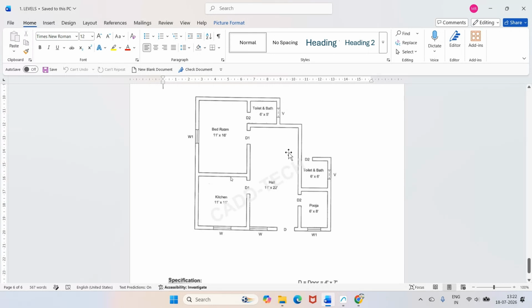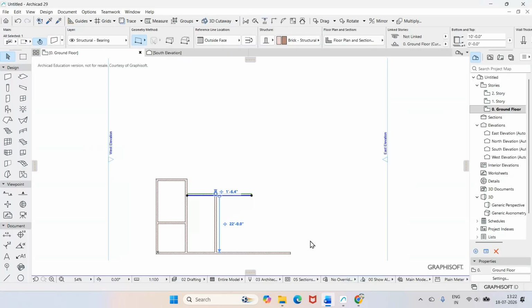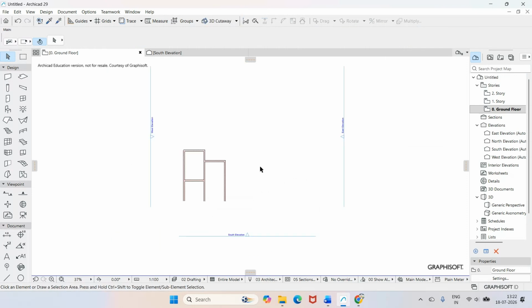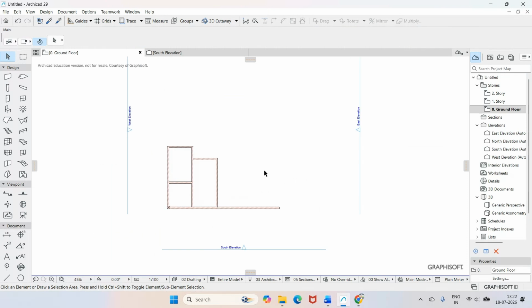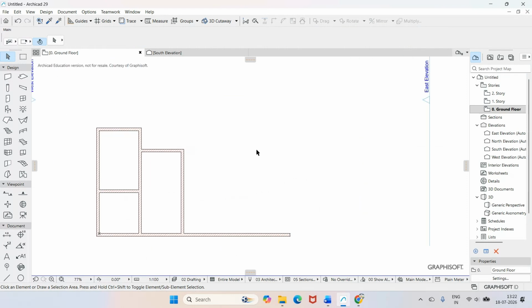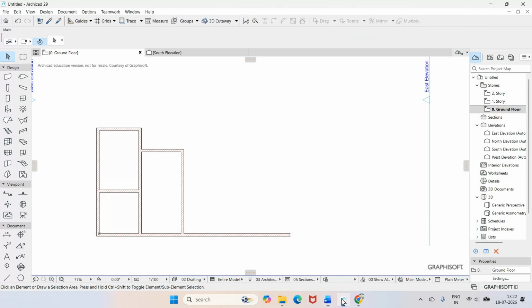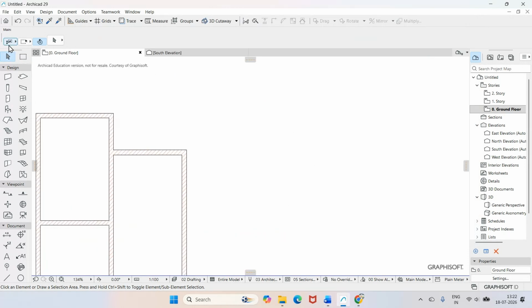Then you just click on this, go to trim on this side, and similarly go to trim, select on this side and cut it. Okay, so once you have this, then the point is I want to take this dimension 6 feet by 5 feet. Okay, so to do that I will go for select.